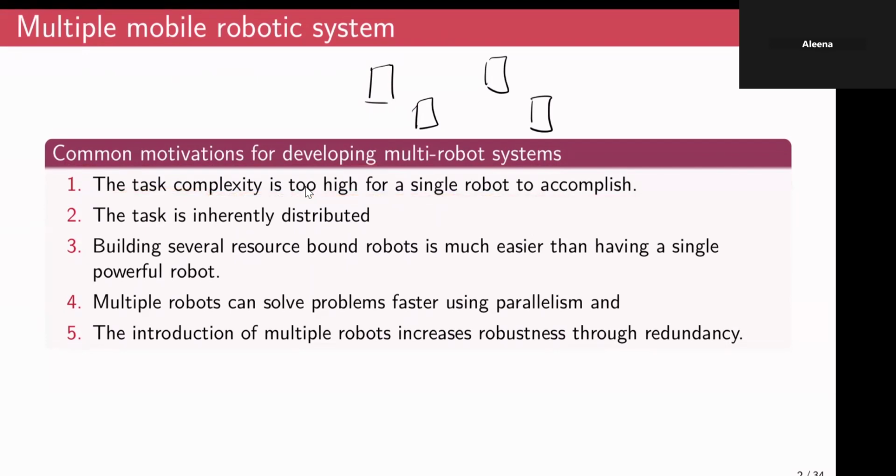It's a pretty straightforward point to understand. One example I could give is in very complex machining processes. If you want to machine a very complex part with very intricate geometries, you could either design a very complex robot which has all 6 degrees of freedom, or you could have a different approach, where you have a planar workpiece bed, which can move in all three directions, x, y, z translations, and a machining head, which can rotate in three directions. So by splitting the 6 degrees of freedom, three for the machine head and three for the tool bed, you can in effect have two simpler robotic systems rather than one complex robotic system.